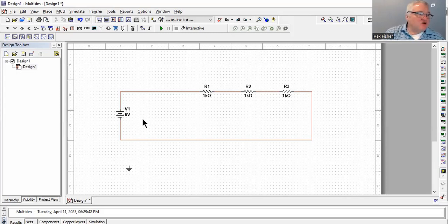Now we're going to measure current with this one. If we measure voltage, we put one lead on one wire and the other lead on another wire, and it will tell us the difference in voltage between those 2 points. So here's our 0 volts. So we need to bring that up here because I want this bottom wire to be the 0 volt wire, the 0 volt reference. And so I'm going to connect that ground to...